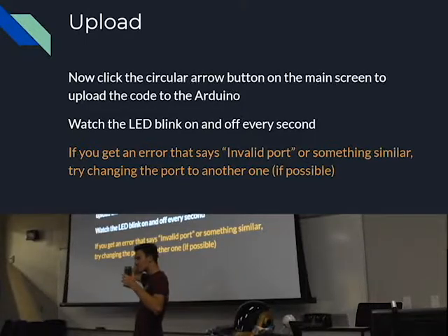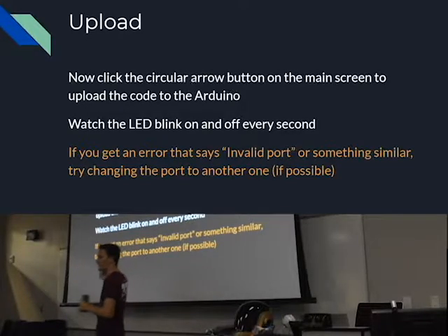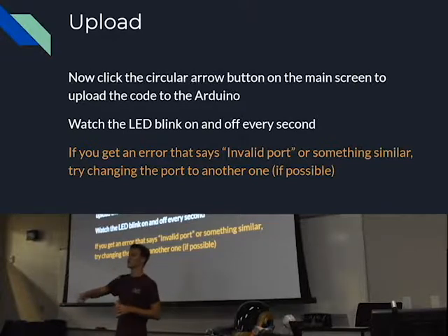That's just something that's built in, but every second it'll go on, wait a second, off, because the next line is digitalWrite LED_BUILTIN LOW. That means turn it off. And then you wait another second.